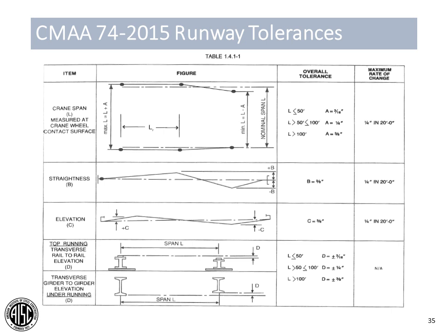But it's a very, very challenging detail to properly detail because it can also lead to stress concentrations if it's improperly detailed. So if you can at all avoid crossing over a building expansion joint with these crane runways, I would advise to do that. But if absolutely necessary, there are ways to do it. I haven't seen a great one that doesn't impose some sort of a stress riser or stress concentration at those splices.